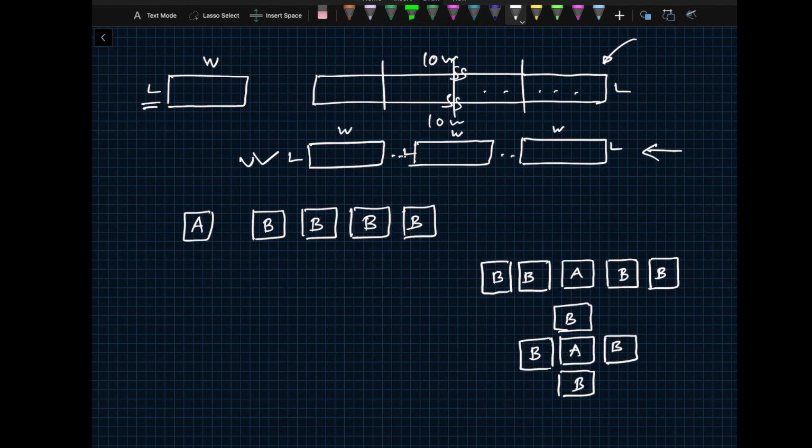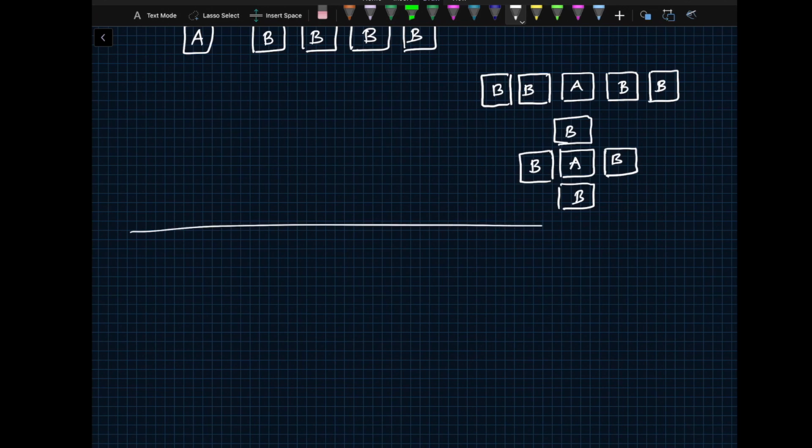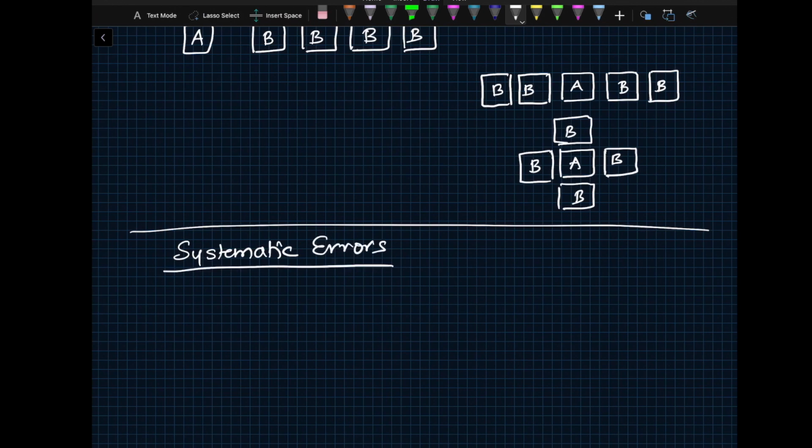So analog design is all about this. Basically, how do you make exact copies in the presence of all manufacturing variations? So this is what we talked about, is all random variation. Now what I'm going to talk about is something called systematic errors. Okay, so systematic errors. When it comes to systematic errors, you can have layout related errors, and I'm going to explain all of them. And then you can have design errors.